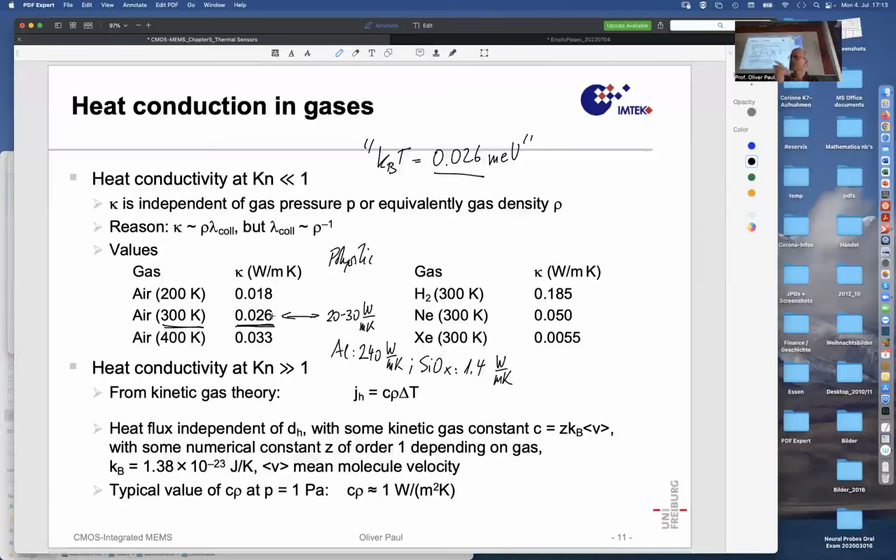That's why this woolen sweater of half a centimeter is good against even minus temperatures out there, maybe for some time. If we were cladding ourselves in a sheet of 5 millimeters of aluminum, I tell you, you would be freezing pretty rapidly because the thermal conduction would be 240 watt per meter per Kelvin. And the temperature outside, wow, that hits you immediately. There is no temperature gradient in between.